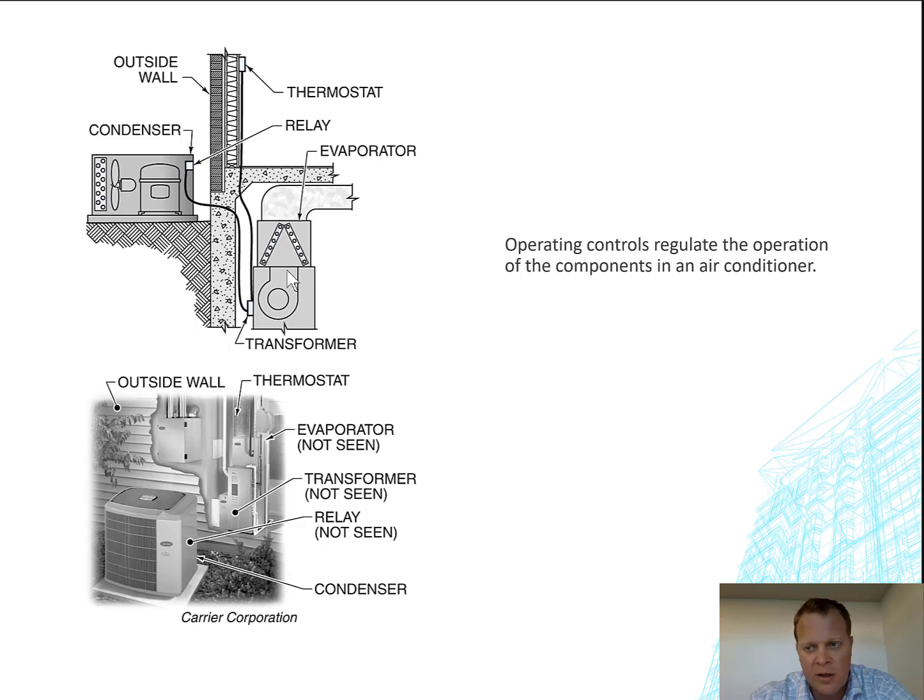non-detailed residential drawing, there are some things like how much space you actually physically need for this forced air unit, as well as the cooling section. What if you have a humidity section in there? That mechanical room itself needs some coordination. It needs to be well planned.